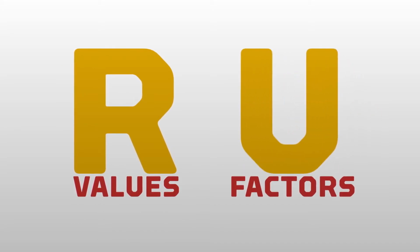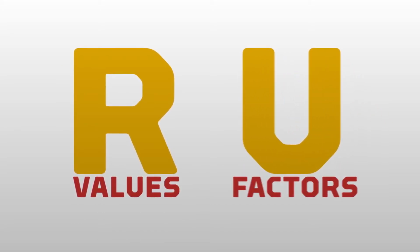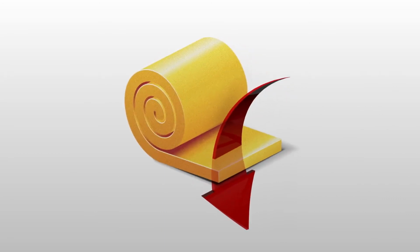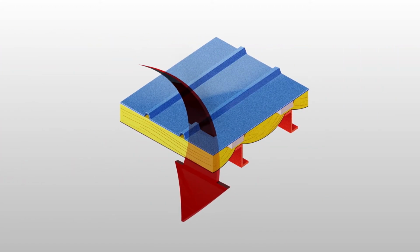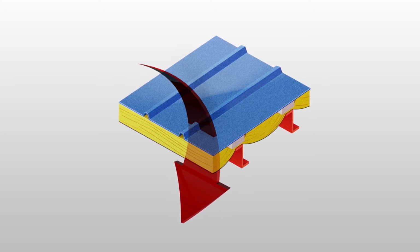Another thing you have to consider is the R value and U factor when deciding how to insulate your building. R value measures the resistance to heat flow. So the higher the R value, the better the insulated product is. And U factor measures the rate of heat transfer. So the lower the U factor, the more energy efficient is the product or assembly. We can help you determine which insulation works best for your situation.